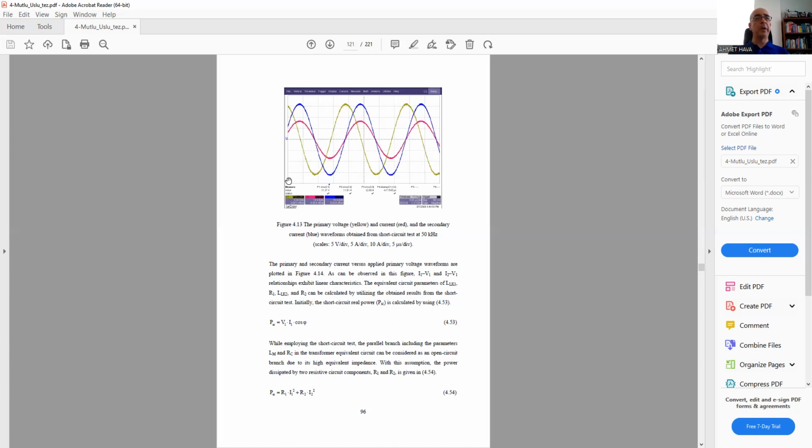So I know I have 5, 10, 15, 20, 25, 30, 35, 40, 50 microseconds, a full cycle. In 5, 10, 15, 20, we have a 20 microsecond cycle of the signal, then we know this is a 50 kilohertz signal. Otherwise, we will not know the frequency of the signal, and then we will not be able to interpret.